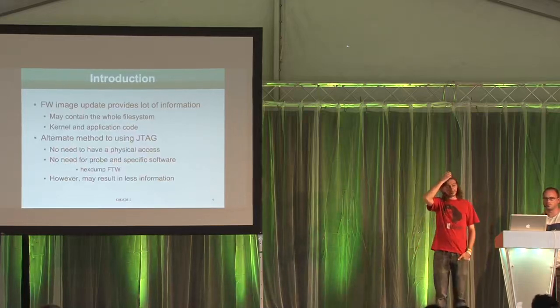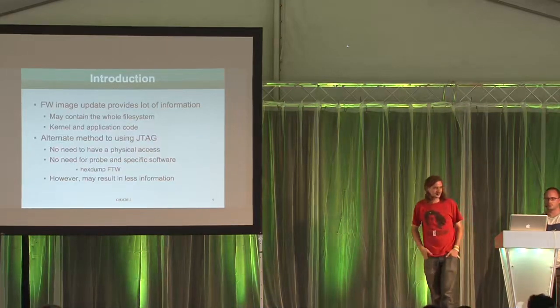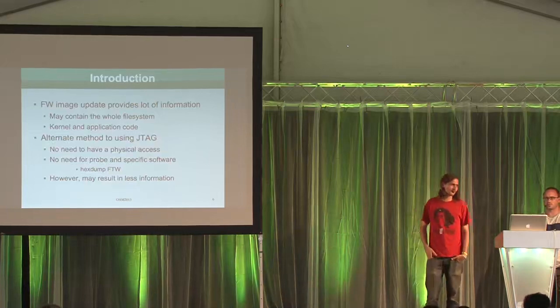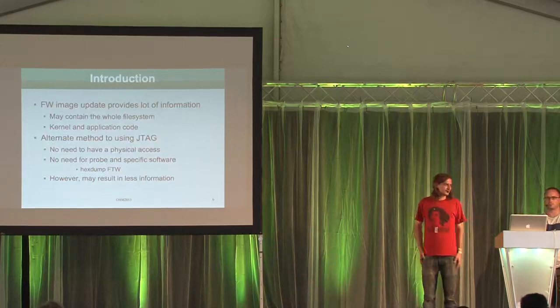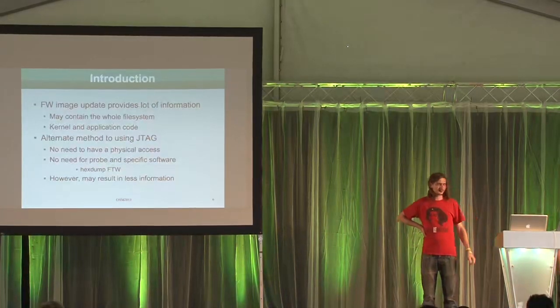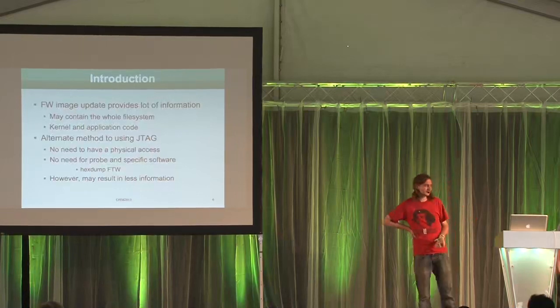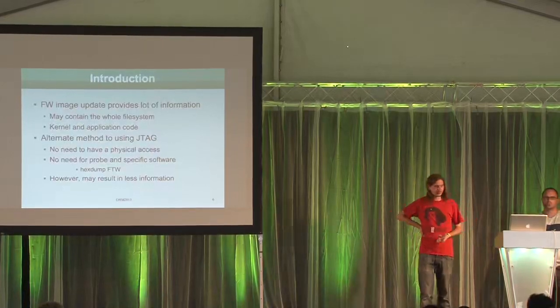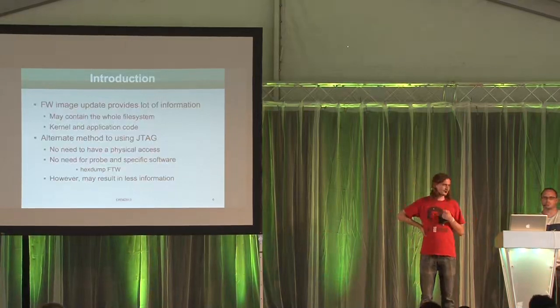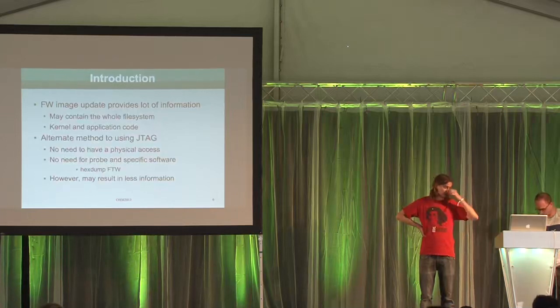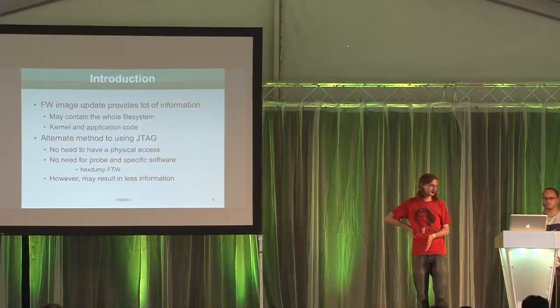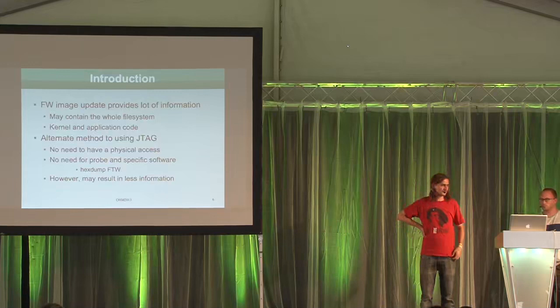Okay, so it's an alternative method of doing it rather than using JTAG, which is the usual way of analyzing an embedded device. The advantage of this method is that you don't need physical access to the device. You don't need any hardware or software specific to JTAG, because for JTAG you need a probe, and you need the JTAG servers that will decode exactly for your processor or DSP, and then you can put a debugger on top of it.